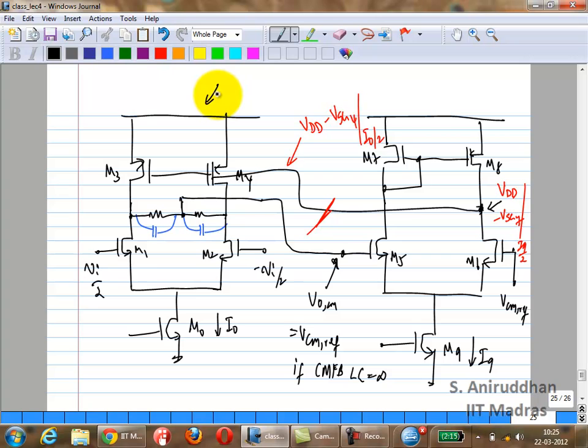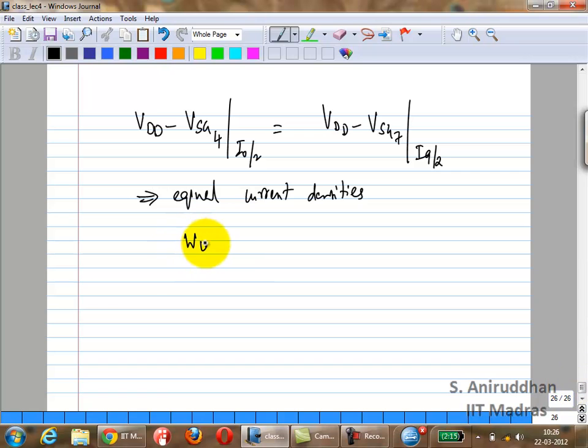You can always choose that, you can just scale down the second op-amp, right? Such that it uses maybe 1/10 the current, 1/10 the size. Current density is the same, still don't have any offsets. Right? You could do that. This is your current density. Is that clear? Actually, not by 2 if you want to be absolutely correct, but yeah.